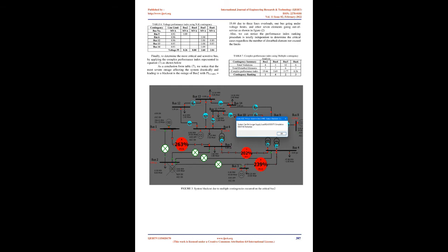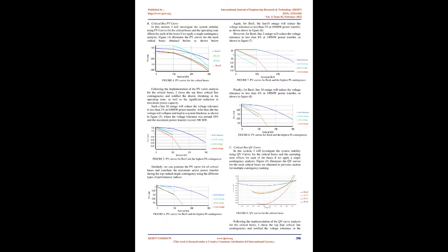3. PowerWorld simulation for single contingency N-1 scenario. In this chapter, we will investigate the contingency analysis for the IEEE 14 bus system using the PowerWorld program. The base voltage and power are considered as 138 kV and 100 MVA respectively. For the base case situation, the total generation is 285 MVA, 272.4 plus j82.4, and the total load is 269 MVA, 259 plus j73.5, and the spinning reserve in the system with losses is 16 MVA, which represents 7% of the largest generation unit located on bus 1.